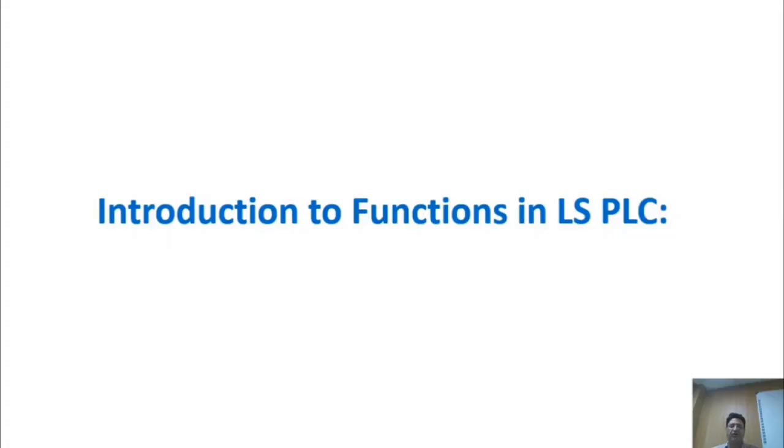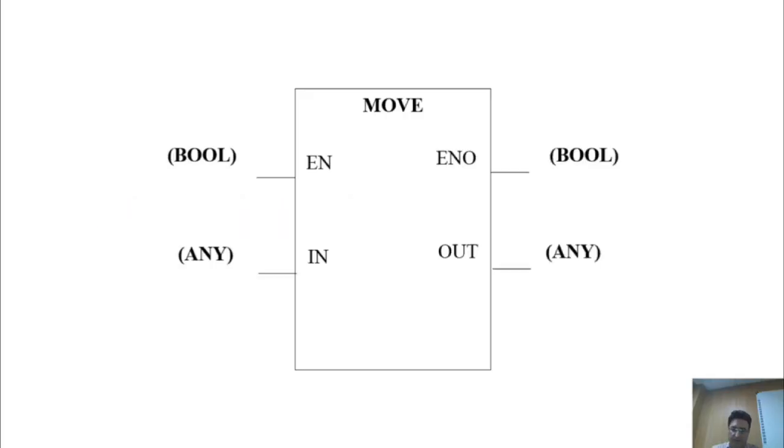In this lesson, we're going to get more familiar with the important functions of the LS PLC. The first function we're going to learn about today is the move function. In the previous lessons, we got more familiar with this function and mentioned that it moves the input into the output, and the data type of the input and output must be the same.